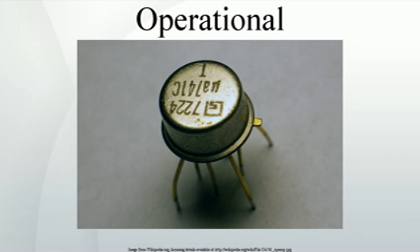Other applications. Audio and video frequency preamplifiers and buffers, differential amplifiers, differentiators and integrators, filters, precision rectifiers, precision peak detectors, voltage and current regulators, analog calculators, analog to digital converters, digital to analog converters, voltage clamping, oscillators and waveform generators. Most single, dual and quad op-amps available have a standardized pinout which permits one type to be substituted for another without wiring changes. A specific op-amp may be chosen for its open-loop gain, bandwidth, noise performance, input impedance, power consumption, or a compromise between any of these factors.